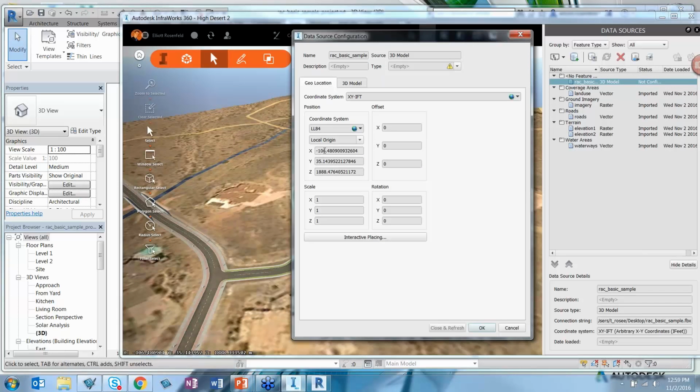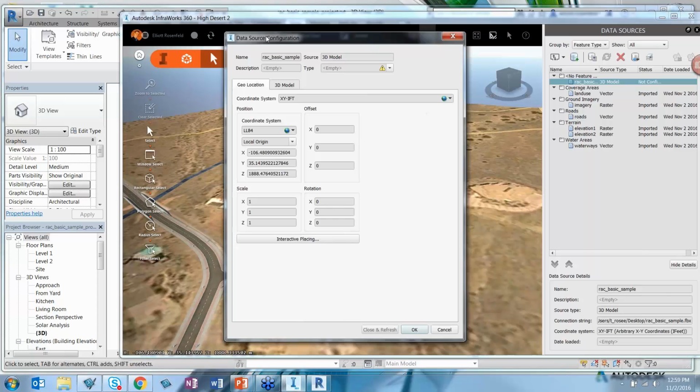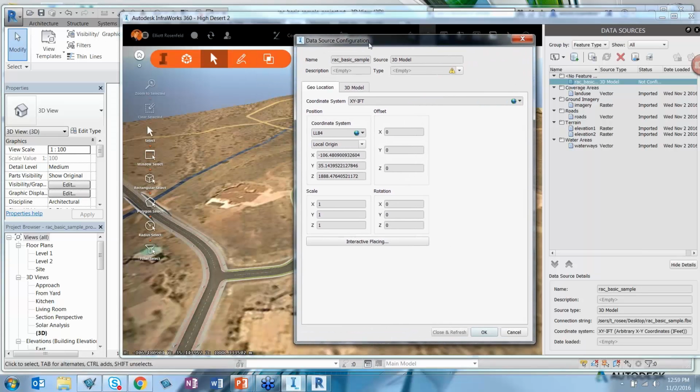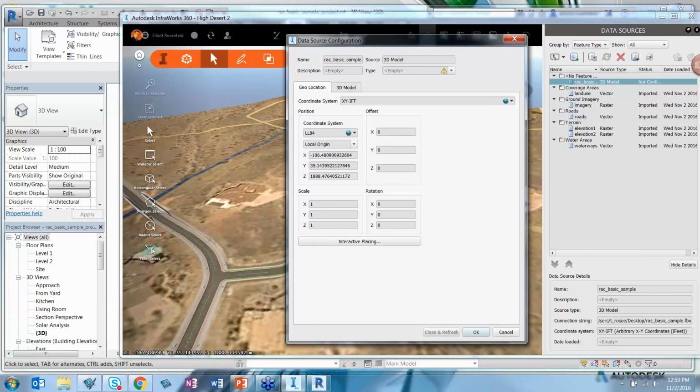And there you have an X, Y, and Z as a basis. I'm going to move quick here because there's only about a minute left. I got a little off track moving too quickly earlier. But the basic point here is that because Revit is assigning your starting point for the XYZ in Revit, you're going to need to use XYZ offsets using a project base point or a survey point.